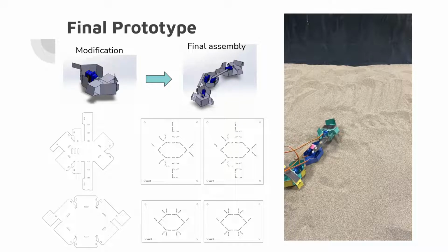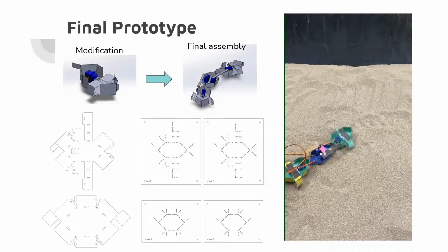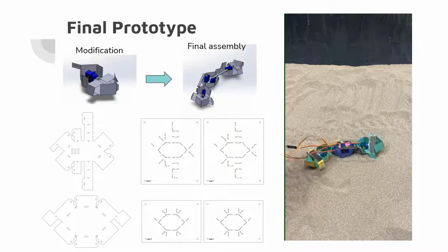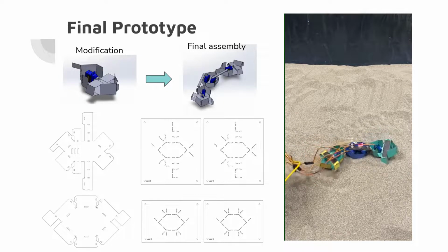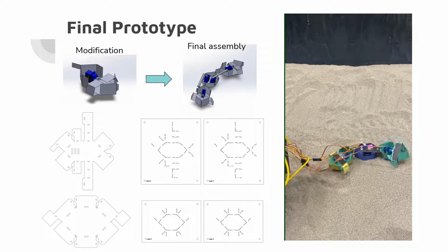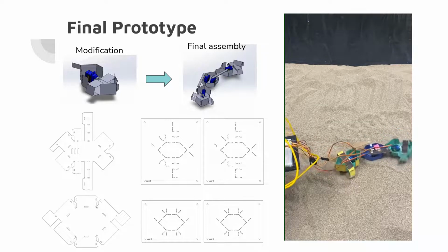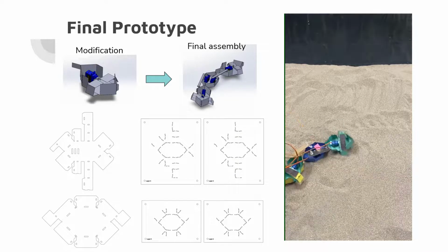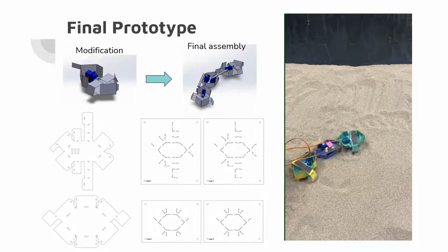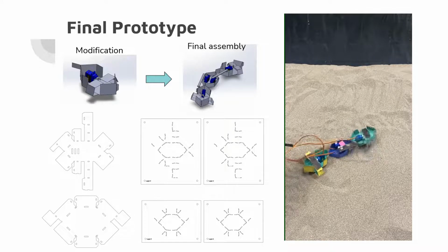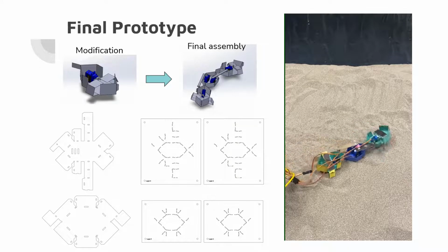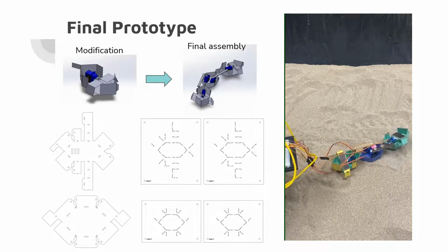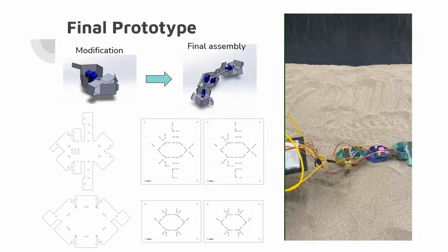Attachment to commercial off-the-shelf parts was actually pretty tricky. We were able to get a screw into the material with some damaging effects due to the laminate layers falling apart. So we basically added extra cardboard layers to reinforce the structure to make up for this. Pins were used at the joints so that it would allow the different segments to still freely rotate about that pin joint.